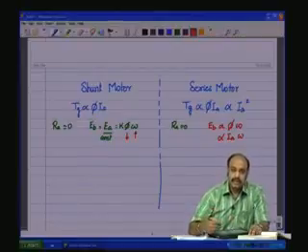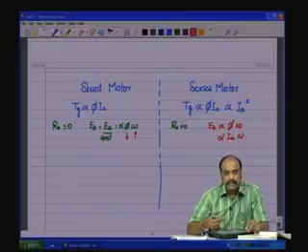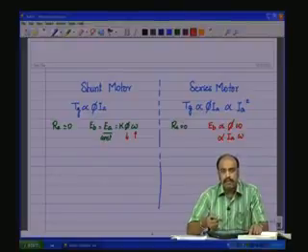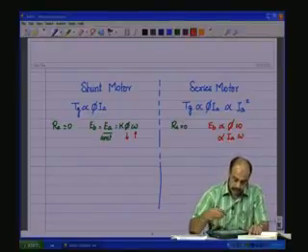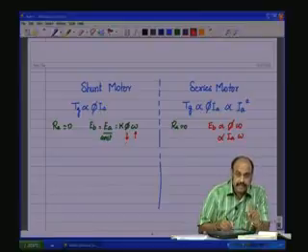But under loaded conditions, the torque will develop and then settle down at the operating point depending upon the load torque requirement. So, the runaway situation can occur in both the cases. In the shunt motor, the runaway condition would be the field suddenly going to 0, when the field winding gets cut.